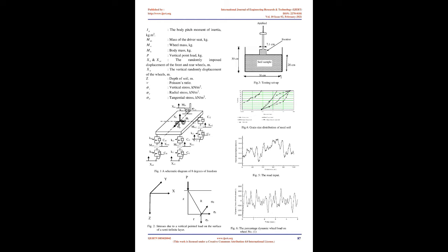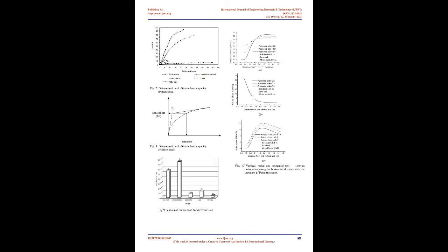Experimental program and procedures. In the experimental program of this study, we measured the load of failure, the ultimate load, that can be carried by the base course samples. All of the experiments were conducted using an automatic compactor to compress the base layers in the model with optimum dry density, Dmax, and optimal moisture content, OMC. The modified Proctor compaction tests were carried out at the laboratory to determine the values of OMC for each sample. Each layer equal to 5 cm, the soil is compacted in the model. Compacted soil finished at 20 cm thick.